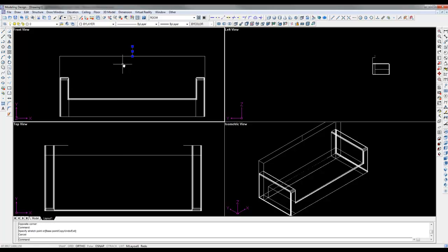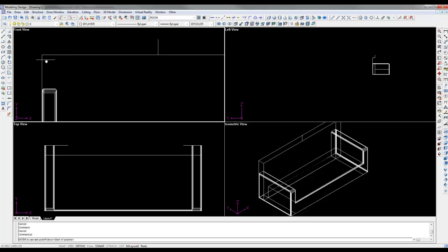Okay. And now using my polyline, I'm going to go and just draw out that shape. So taking ortho off, I'm going to use my arc option. As we can see, our arc is a bit too intense, so I'm going to use D for distance, or direction I think, and then just give it a bit of a smoother one. So I click once, you can see it gives it a gradual curve. Okay, so to about there, and then I will finish off at the center, which I'll snap to.